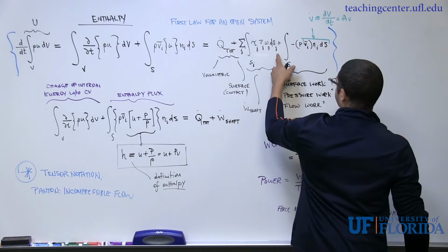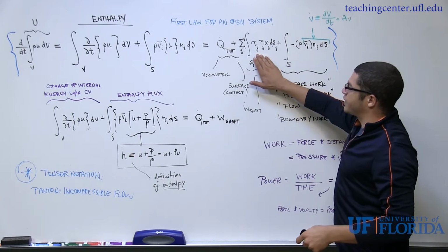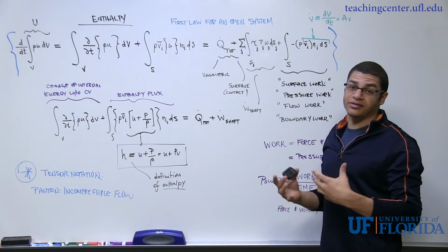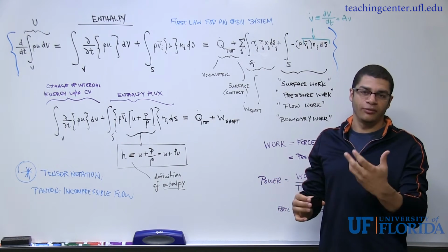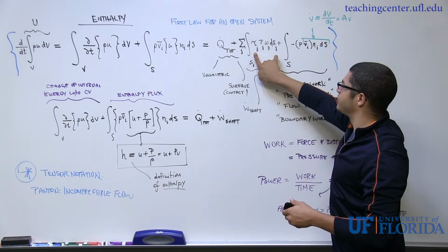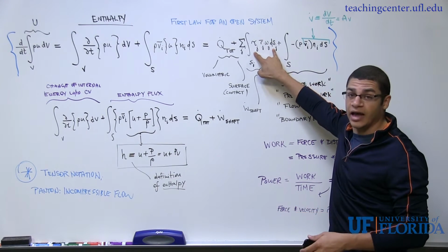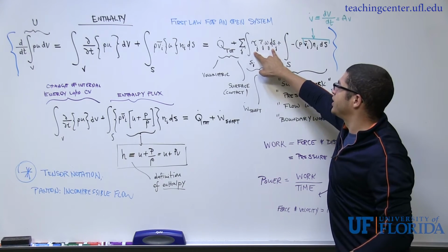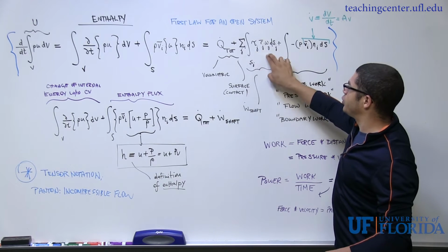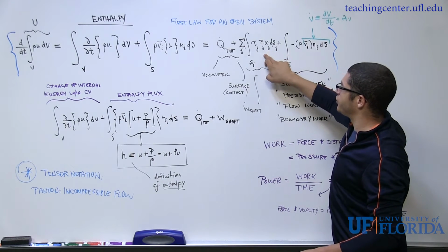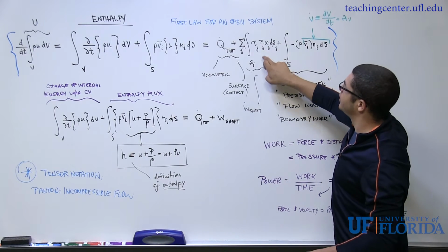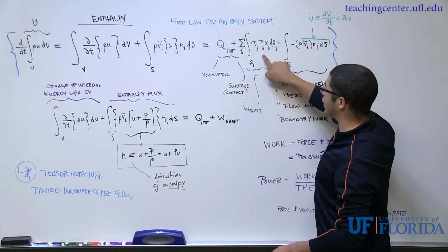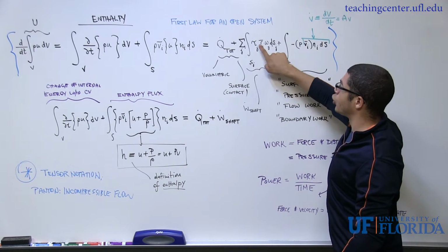So let's check the units here. We've got tau sub j, which is the shear stress distribution on the shaft. That's essentially stress and pressure, the same thing, a force per unit area. If I multiply it by a differential cross-sectional area element, I'll get a shear force distribution on the shaft. That shear force distribution is then multiplied by this inner product, which is the radial distance from the center of the shaft times the angular velocity of the shaft, which gives me a tangential velocity around a circle whose radius is r bar sub j.